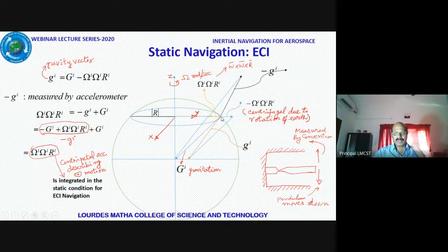So you see here, the vertical z-axis displacement is zero, and therefore there is no acceleration in this direction. There is no position change or velocity in this direction, and they will remain the same. There will be only an initial z value that will be the position, but velocity and acceleration are zero. And that is a check, in fact, whether our inertial navigation output gives any z component. A small z component will come, and that is due to algorithmic error and other errors.